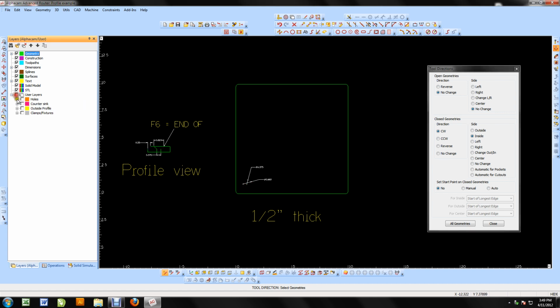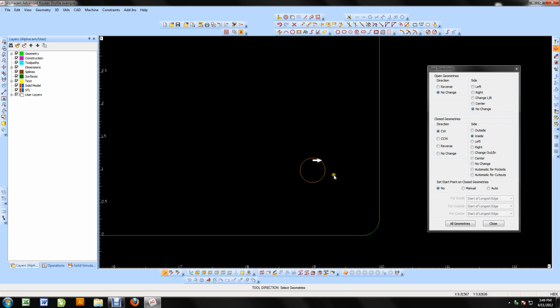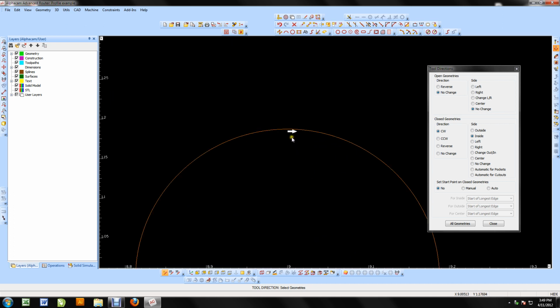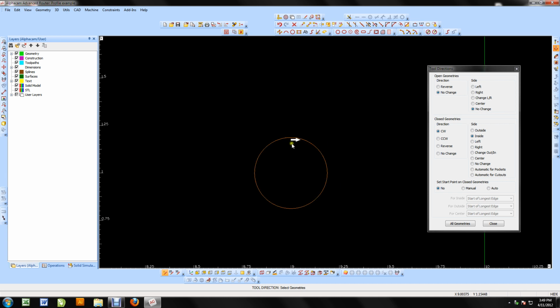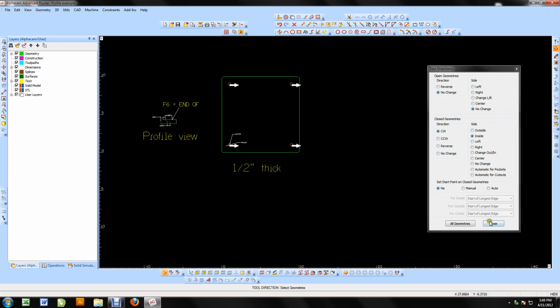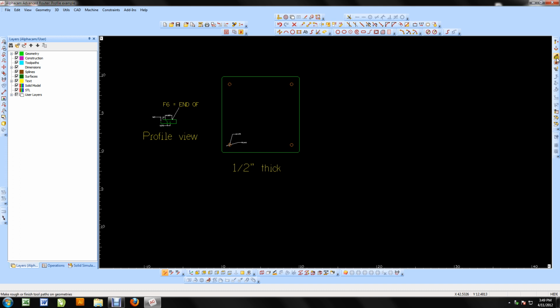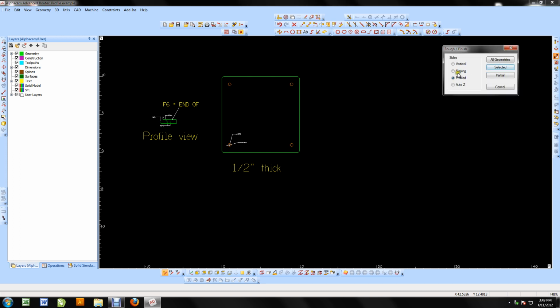and I'm going to have everything in layers, so I'll shut off my layers and just turn on those holes that I want to do. And I'll just put a bounding box around them. That's going to go around the inside of those holes. If I zoom in, you can see the little ghost tool there that shows me which side of the line I'm on. I'll close that. Now I want the sides to be vertical, straight up and down the sides of those holes.